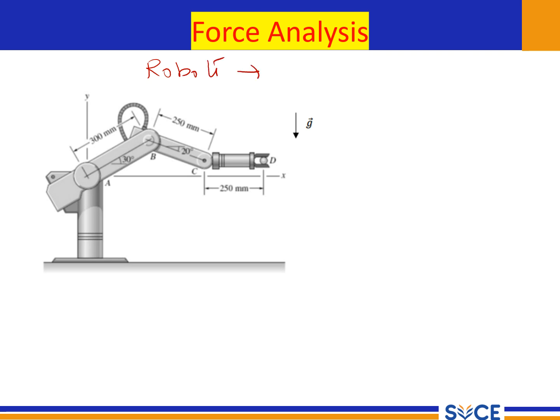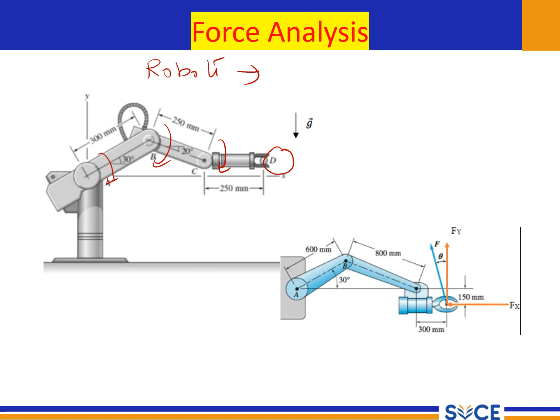Because here our main objective is to determine how much force is required to move each and every part of this robotic arm, so that I can move a mass which is going to be picked and placed by a robot. So this is once again a force analysis. I have to analyze the forces acting on each and every arm by calculating the weight which is going to be lifted by the robot.